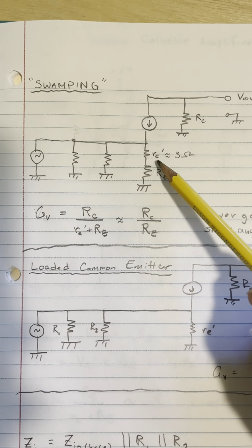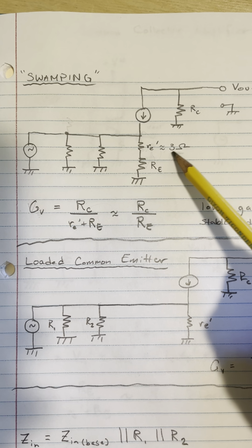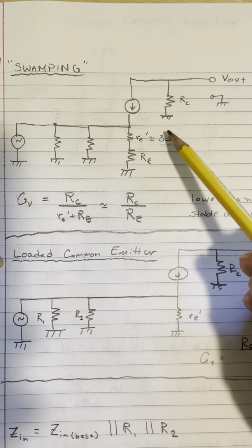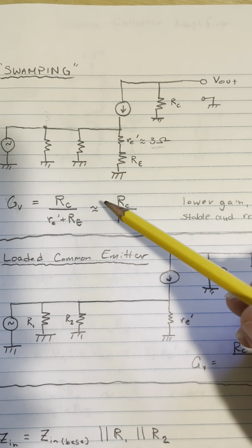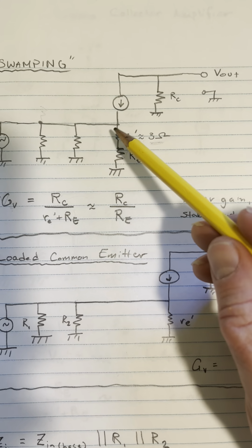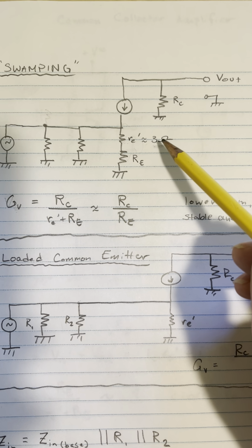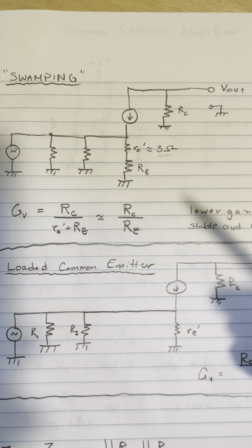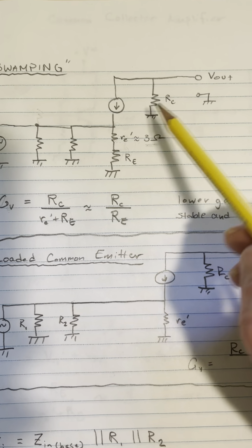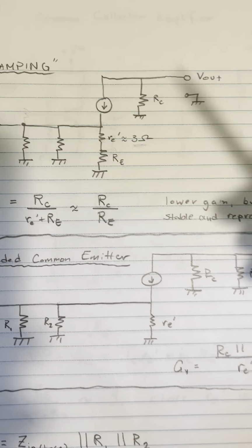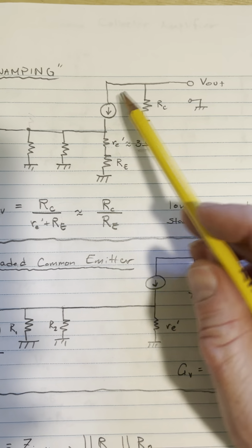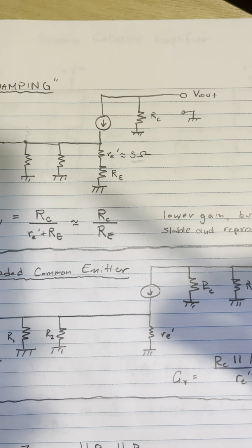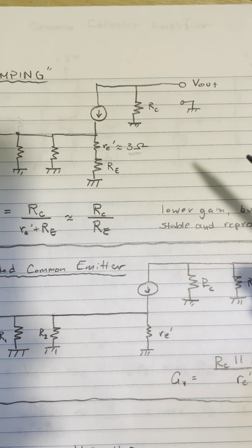Well, RE prime is a very, very sensitive resistance value. It depends highly on temperature. And from resistor to resistor, yields are not very uniform. So you might have one resistor with a resistance of 2.5 ohms effectively, one with a resistance of 3.5 ohms. And if you take a large number divided by a small number that's moving around by a lot, you get a fairly unstable gain. So depending on the particular resistor you use and particular environmental conditions like temperature, the gain can vary a lot.